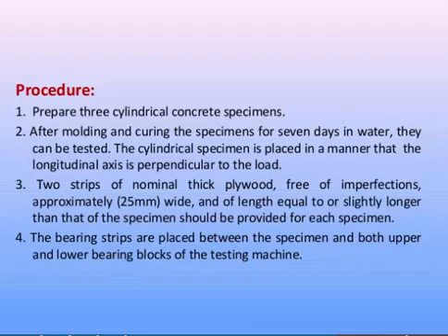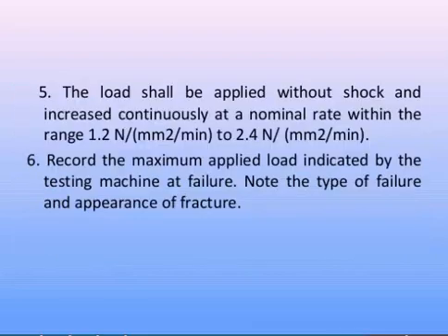Apply the load continuously without shock at a rate within the range of 0.7 to 1.4 megapascal per minute as per the IS code, or 1.2 to 2.4 megapascal per minute based on IS 5816-1999. So the load shall be applied without shock and increased continuously at the nominal rate within the range of 1.2 to 2.4 megapascal per minute.